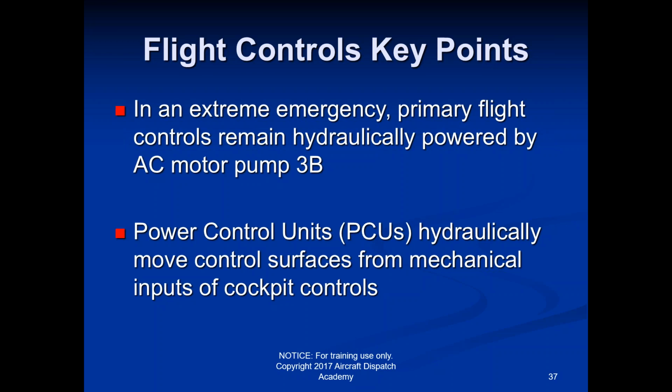So sometimes those go bad because, like it says here, it's the one that actually controls the hydraulics to all of those different flight controls, and it's based off of whatever the captain and first officer are inputting in the cockpit. So it's like a computer, really. It says power control unit, but a lot of times they'll call it a computer. It's reading and then basically carrying out what it's being told to do.